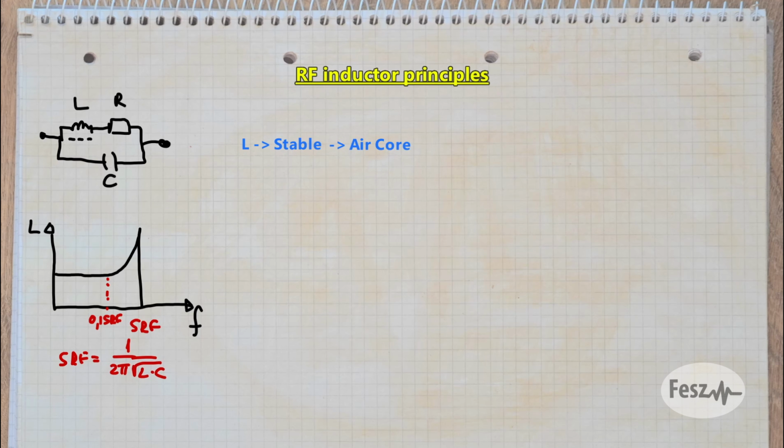In other words, a good inductor has a high self-resonant frequency and in turn low parallel capacitance. This is normally obtained by using a single layer of turns and spreading the turns out, since this capacitance occurs in between the turns. Lastly, a good inductor is considered to have a high Q factor, which is a different way of saying that it has low series resistance.